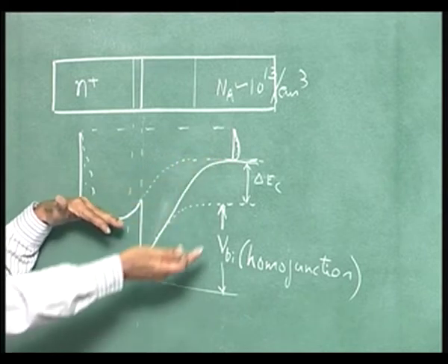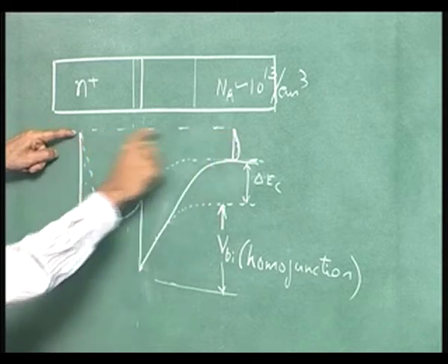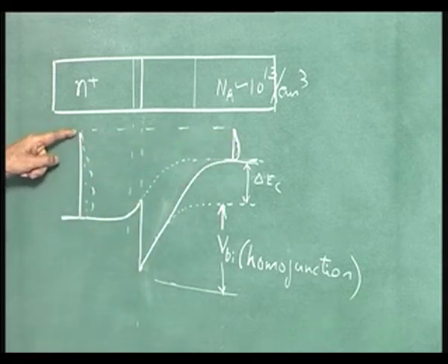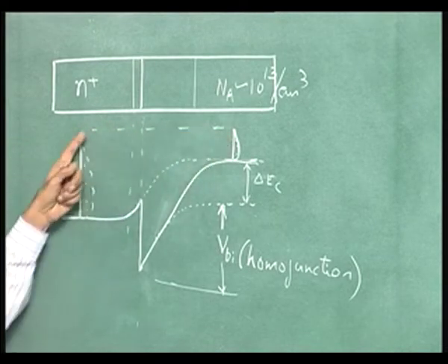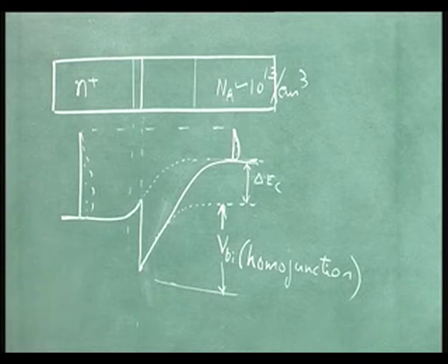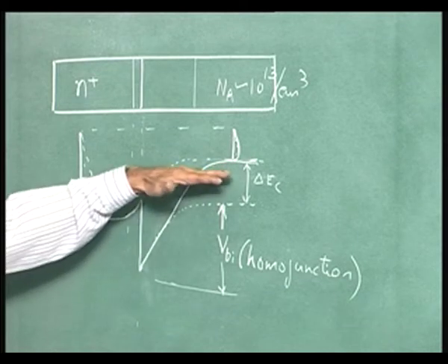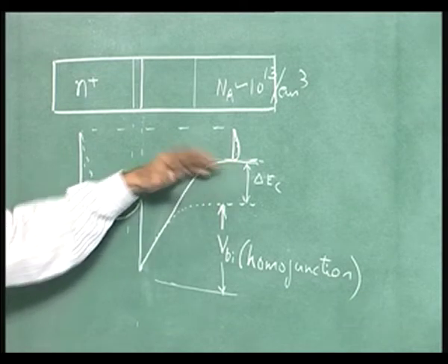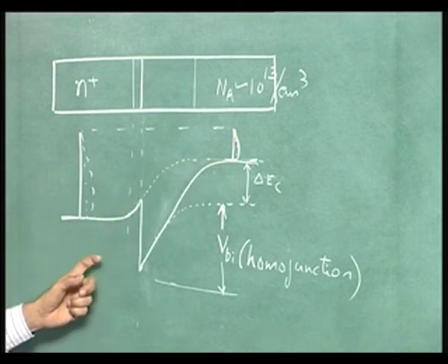And the built-in potential builds up till you can see the carrier concentration is equal there, okay. It is like the war between the two. So, once these are equal, that is at the same level, the maximum energy of electrons, no more net flow of carriers, current is 0, thermal equilibrium situation. So, this band edge keeps on rising here by transfer of electrons from here to here till this is raised up to that. That is the built-in potential.